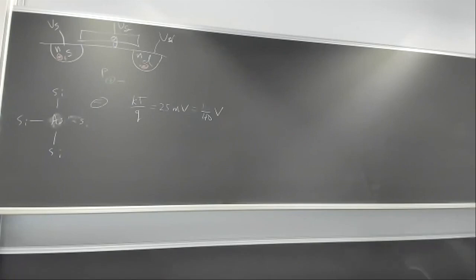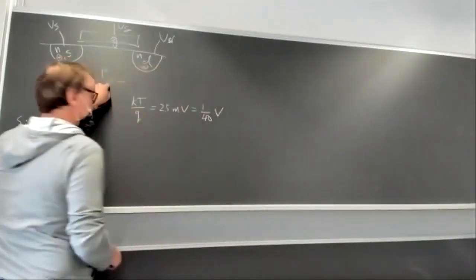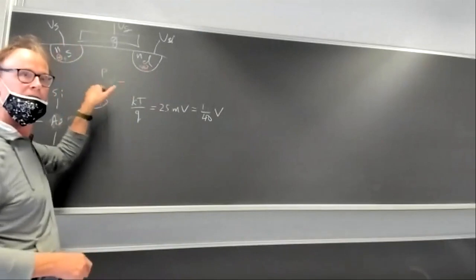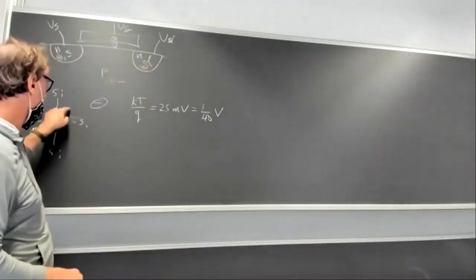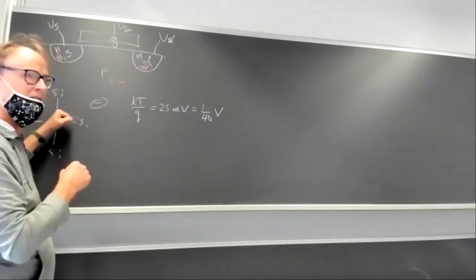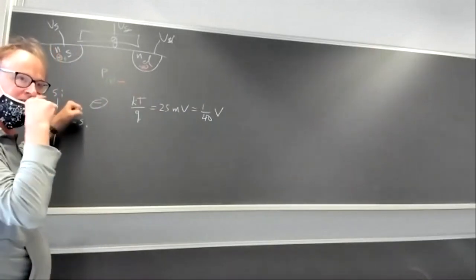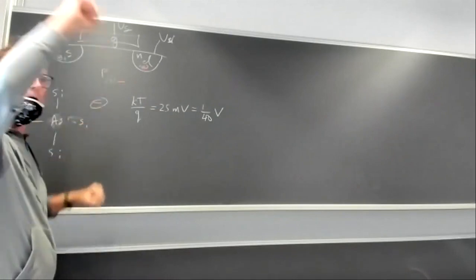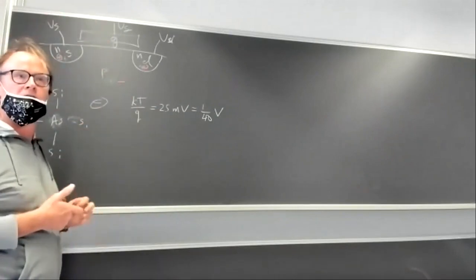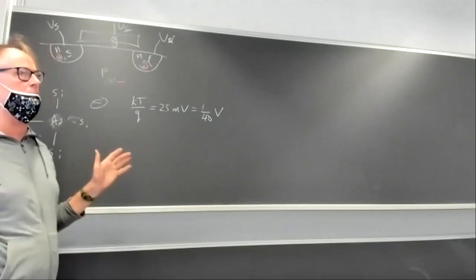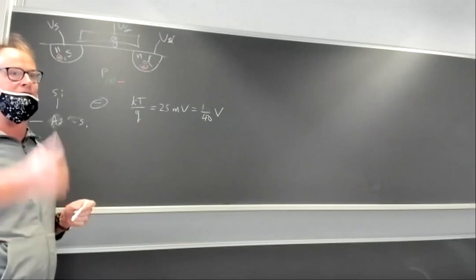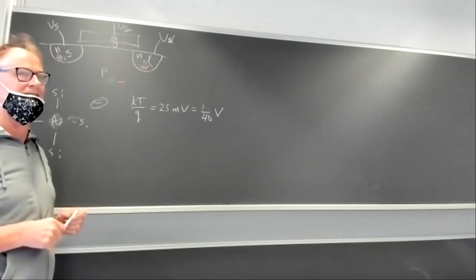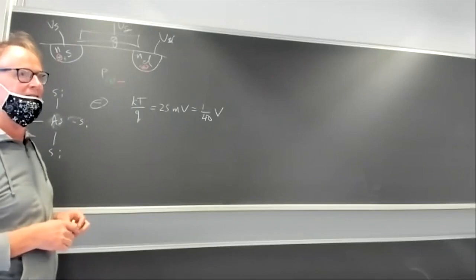Okay? And in the p-doped one, you have fixed negative charges and free positive charges. Yeah, free holes. There are holes whizzing around here. Holes are positive charge. Because to get a hole, you have to actually take an electron away from the atom, so it leaves a hole in this cloud of particles. But just think of it like positive and negative charge, you'll be fine. It's just that you can't actually physically get a hole out of the silicon into vacuum, normally.